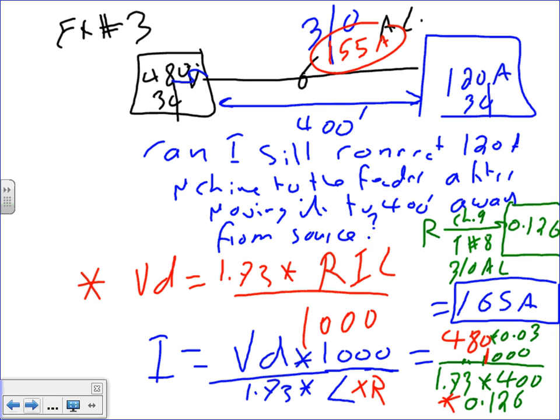So what happens, guys, if I came up with 100 amp? Then my machine cannot be hooked up to the same conductor that was feeding it to start with, so you have to go up on your conductor. That's a situation where you use the amps. You need to find how much amp I can get out of this conductor. Because most of the time we don't do it this way. Most of the time we size the conductor to feed the amps.